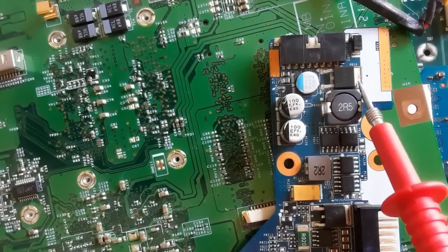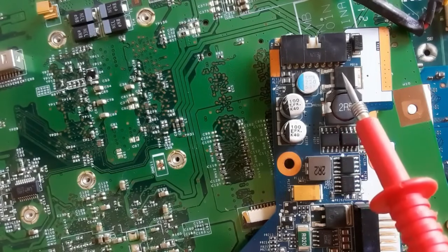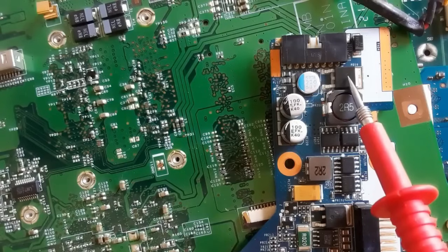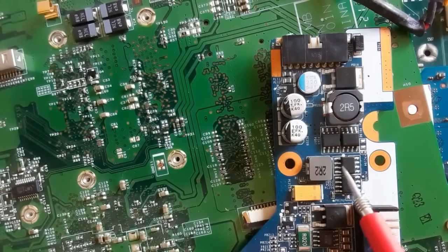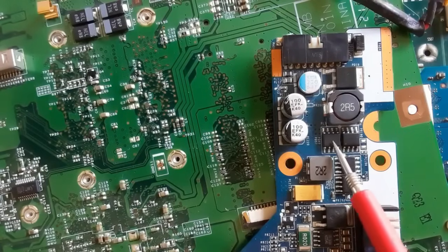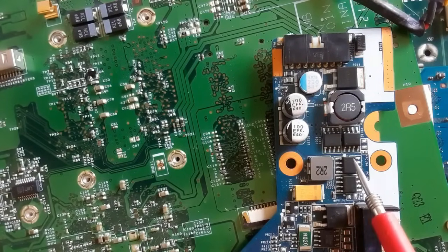Here, as you can see in this motherboard, this is another MOSFET with 3 terminals. Okay, so this is a switch. For this motherboard, just one MOSFET. For those MOSFETs, as you can see, those are for the 3 volt and 5 volt power system. These 4 MOSFETs, 2 generate 3.3 volt and the other 2 generate the 5 volt.